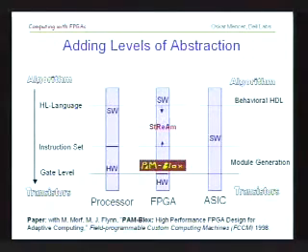Looking at the levels of abstraction, if we compare microprocessors, FPGAs, and ASICs here, we have in VLSI synthesis software that maps all the way down from an algorithm down to the gate level, has ultimate flexibility, and there are levels of abstraction that the people have figured out that they want to go for, and have different tools to do that. For FPGAs, what I'm suggesting here is to have the module generation and the domain-specific compilers on top of that that map down to these particular module generation environments.